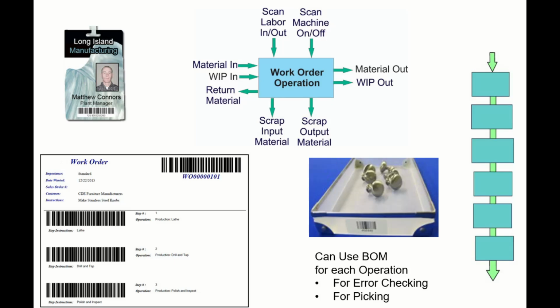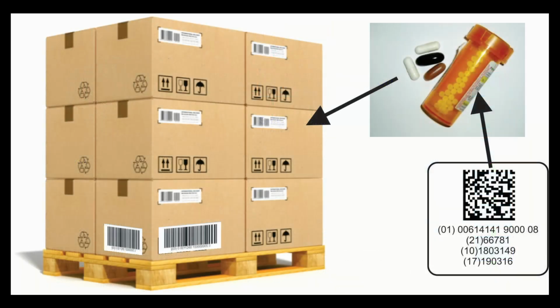It enables BellHawk to warn the operator if they are about to make an operational mistake, such as using the wrong parts. This also enables BellHawk to record related data, such as serial and lot numbers, and expiration dates of the materials used. In addition, work-in-process materials can be tracked out of one step in the route of manufacturing operations and into the next, possibly with permanent LPN tracking barcodes attached to each tote. Finished containers of products or serialized items, assemblies, and kits from each work order can have LPN tracking barcodes attached, by which they will be tracked.